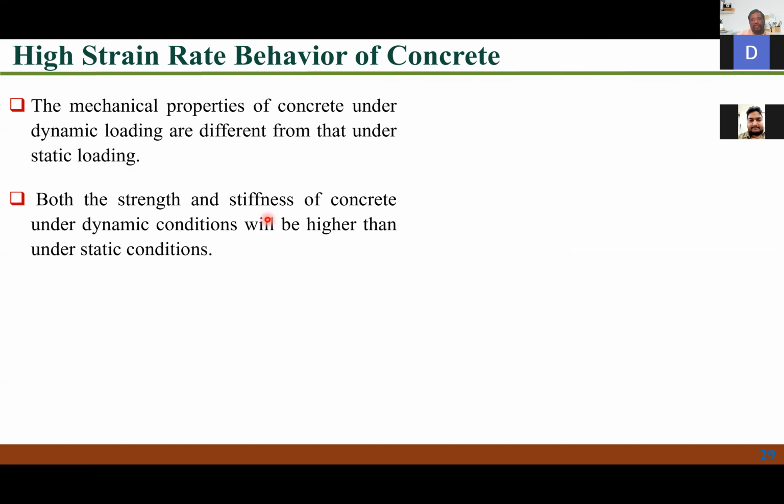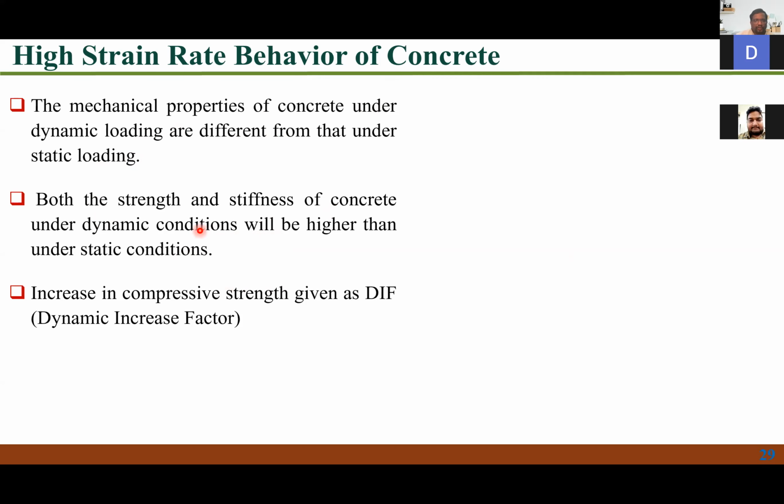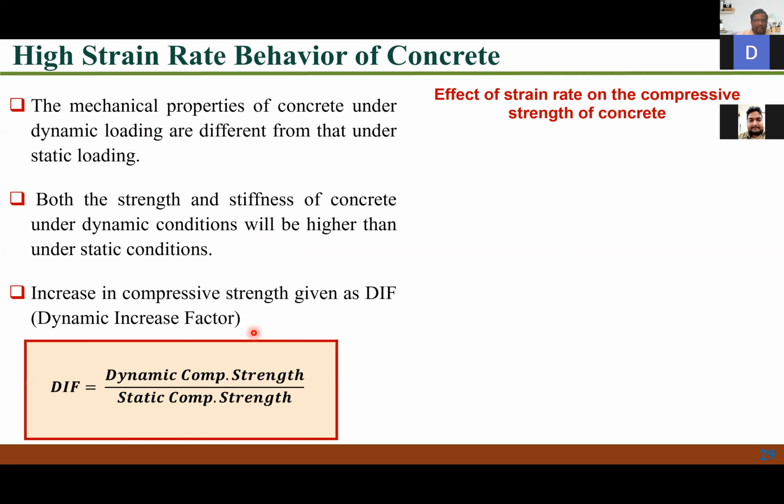Both the strength and stiffness of concrete under dynamic conditions will be higher than what you get in static conditions. This increase in strength we call the dynamic increase factor. The dynamic increase factor is the dynamic compressive strength divided by the static compressive strength.